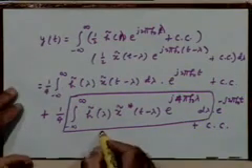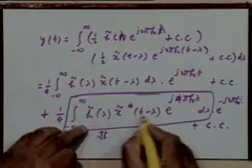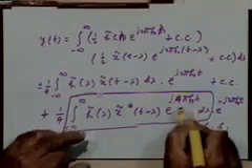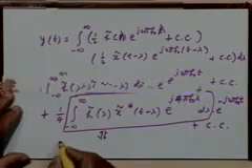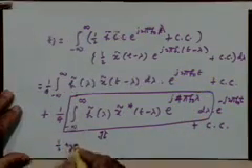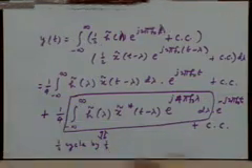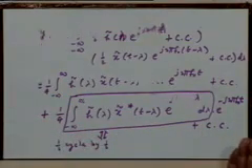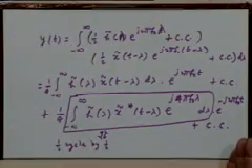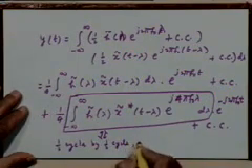So basically the argument that we give here is based on the fact that this is a low pass signal and this is a high frequency band pass signal, right? And therefore, half cycle by half cycle, this kind of argument is very useful in communication theory, because otherwise you get stuck with integrals which you can't evaluate. So half cycle by half cycle, the integral becomes 0.